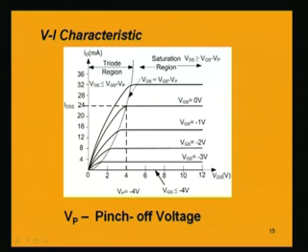So, if VGS is less than minus 4 volt, then obviously the drain current will be 0, and that is shown by this line, the line which is just coinciding with the 0 line on the VDS axis. That is called the cutoff region, the device is turned off.